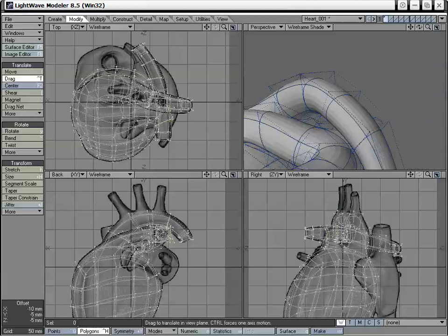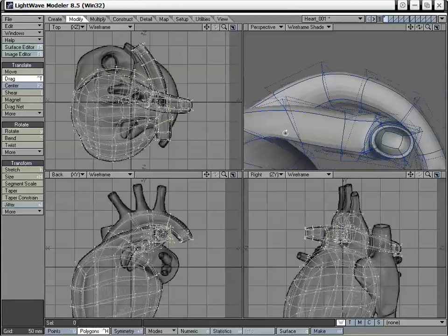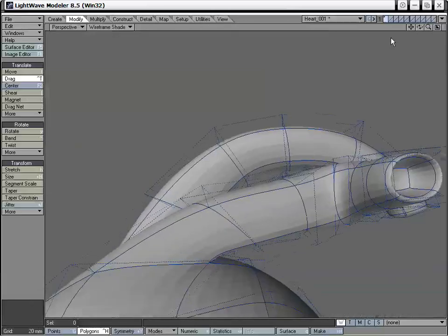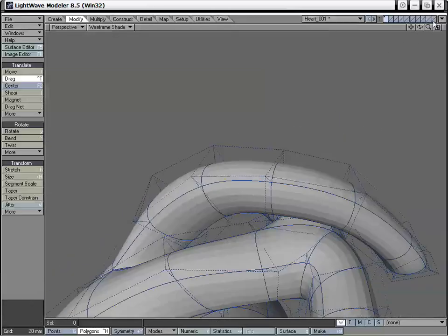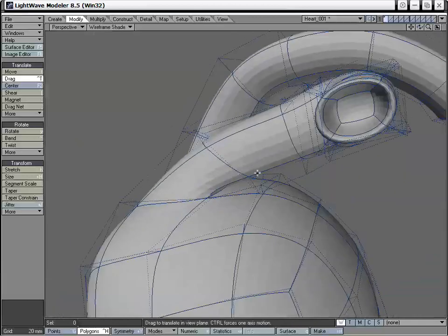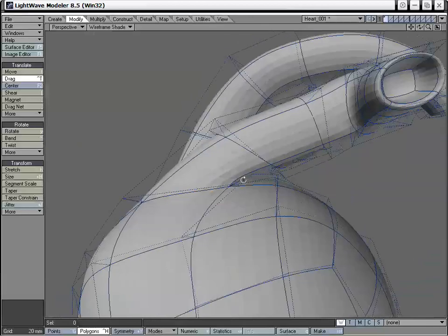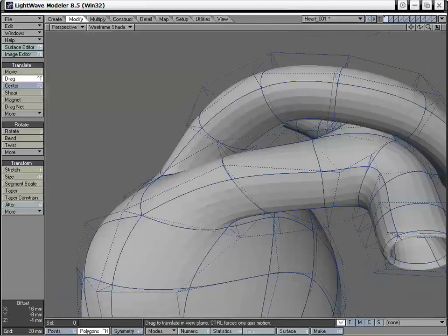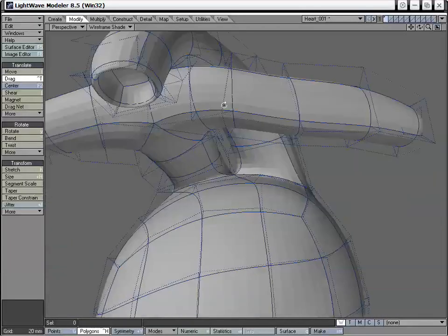And like I said before, we are going to be metaforming this, so we will have a lot more geometry to work with, so we can make this a lot rounder and a little bit cleaner looking. And I'm just going to expand that full view, which I did by clicking this button up here. Or you could hit 0 on the number pad with the cursor moved over the viewport, and it will expand it to full view.